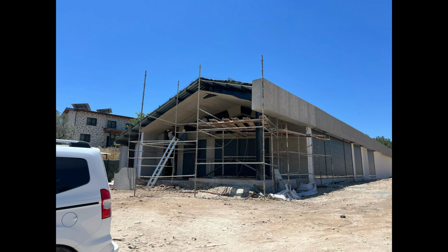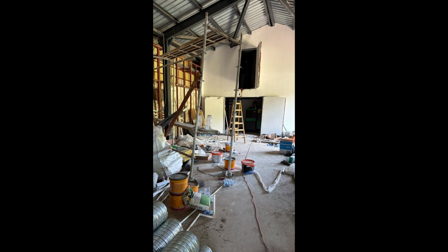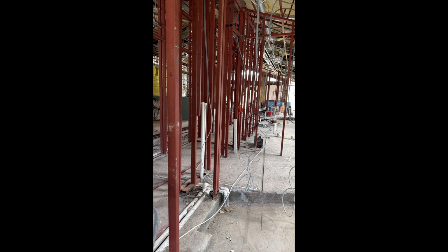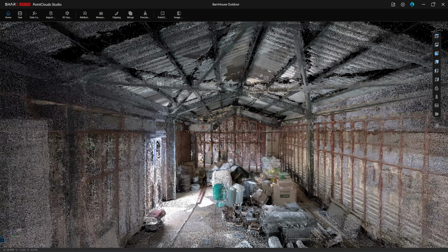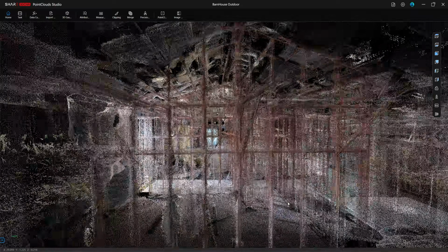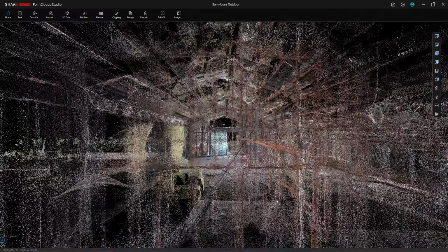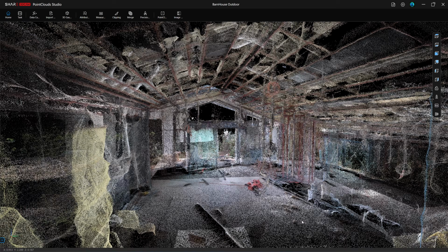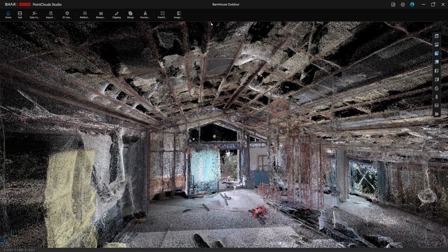Construction has already started on the site and there are quite a few obstructions for the scanner. This level of obstruction is pretty normal, and to capture as much of the main structure as possible, you need to move around to different positions to eliminate blind spots. The black steel frame you see is the main portal frame of the building and is the key dimensions for modeling. The red painted sections are the interior drywall frames, which will be removed and excluded from the model.